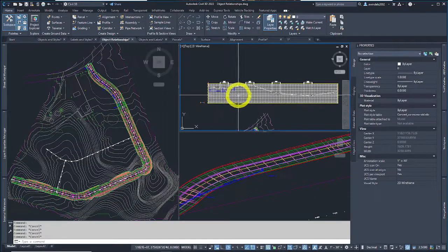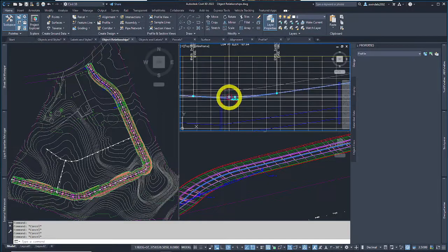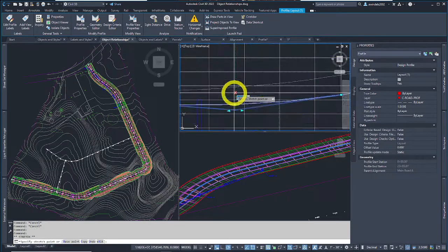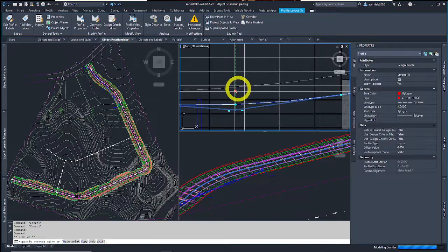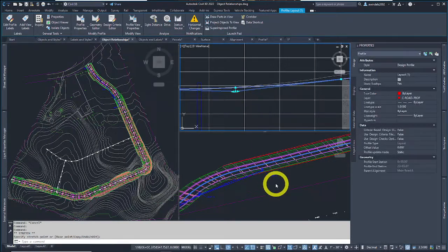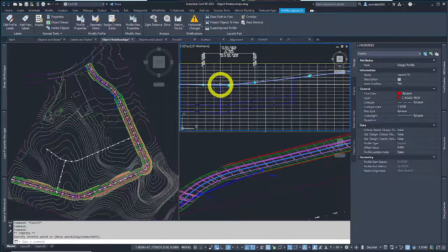That's not a bad work path, especially if you're trying to visualize things. All we're going to do is pick this profile, this black line, and change the PI. We're just going to bring it up a little bit this way. We're changing the elevation of the road quite literally. Everything's linking. You saw down here, things were happening. I might have to change it more drastically, but you can see this moved with it.